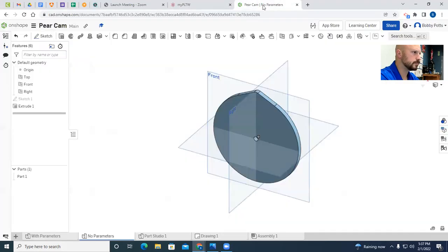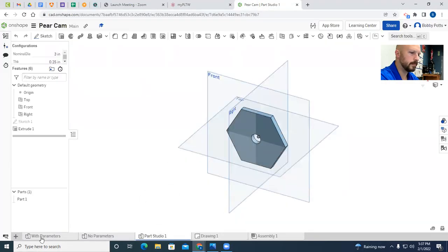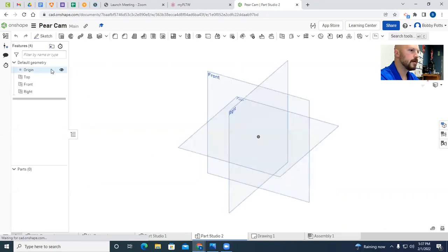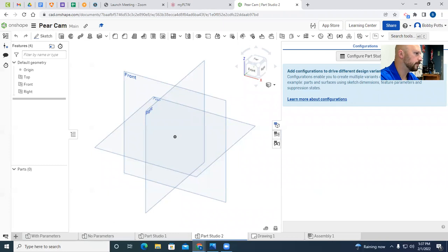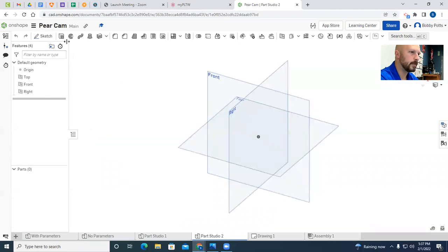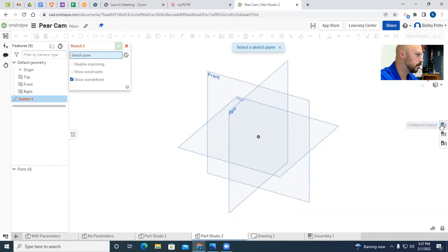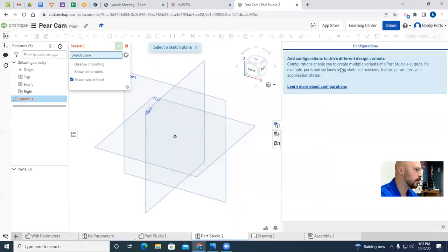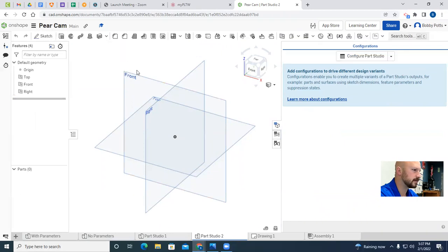So to make this, before you click anything, if you click sketch, this next part isn't going to work or show up for you. But over here on this right side, you've got 3 little tabs. Okay, we want to click the first one that says configure panel. Now up top, you have this little chart. But if you've already clicked sketch and then you go over here to it, now there's no longer that chart option. So I have to clear out the sketch. Now I can create this.